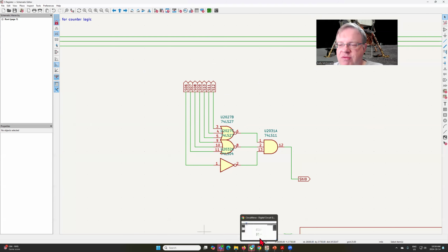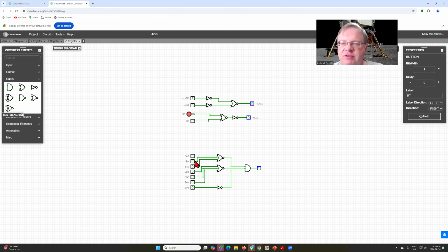Let's pop back over to our simulator here, and we can see how this logic works. If any of these contain a 1, this will drop low, but if everything is 0, we'll go high, and we'll use that to determine whether we're running an editing control instruction, when combined with both S3 and S4 being 0. And from there, we'll be able to start doing our shifting back and forth.